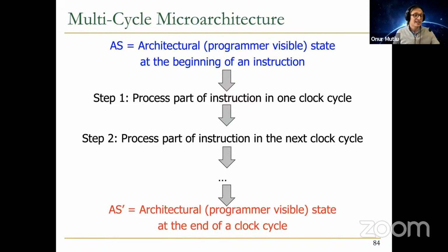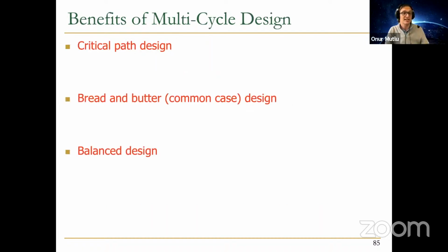An add instruction can have, let's say, 5 states in that machine. A load instruction can take maybe 100 states, depending on the complexity of the instruction. The string copy instruction that I mentioned, that copies, I don't know, 100,000 or a million bytes from one memory location to another memory location, can take 1 million cycles or longer. A million potential states, right? Or it can stay in each state much longer to do the operations, right? Basically, you're not limited by a single clock cycle anymore. So the opportunities for optimization increase significantly.